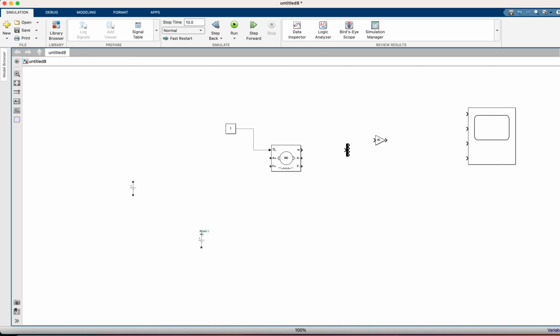So we need to connect our field voltage source to the fields, the positive of the field voltage source to the positive F, and the negative to the negative F. Here armature voltage, the negative to the negative A, the positive. Now since we need to control our DC motor with the armature, we need to connect our armature voltage to a resistor.